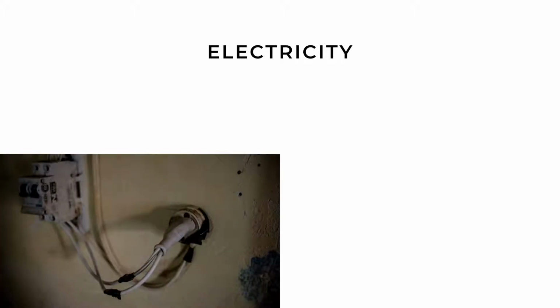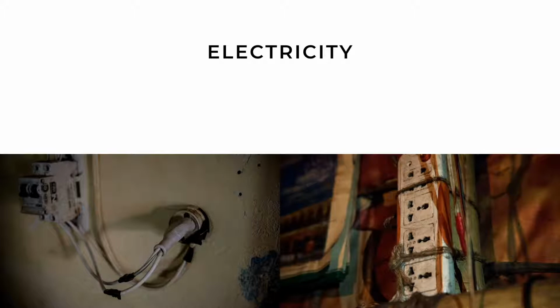You can also obtain electricity by using a gas-based generator required to convert the chemical energy found in biogas into electricity. The equivalent of 6 kilowatt-hours of heating energy is contained in each cubic meter of biogas. About 2 kilowatt-hours of usable electricity can be obtained when biogas is converted to electricity. The remaining biogas is converted to heat, which can be used for heating applications.